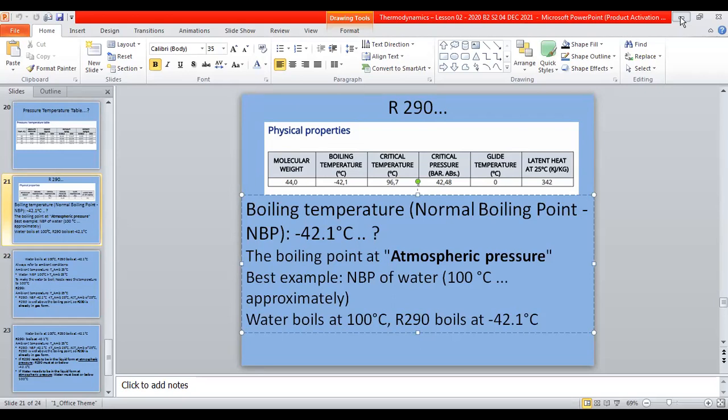So we have to keep the gas pressurized so that we can have liquid. The reason is simply that the normal boiling point is very much lower than ambient. So when this comes out from the hose, it immediately turns into gas form, unless the ambient is below the normal boiling point.